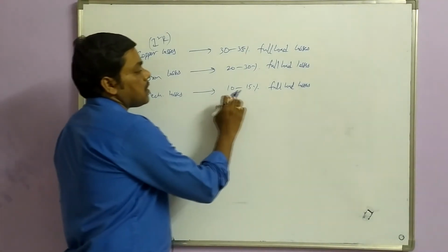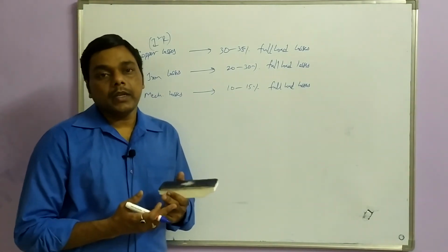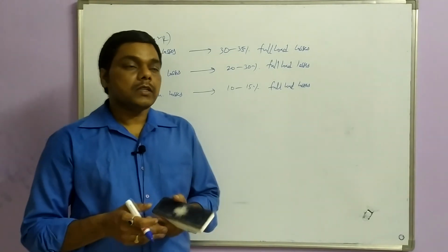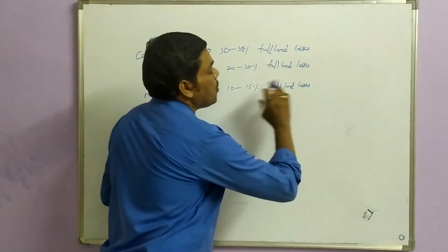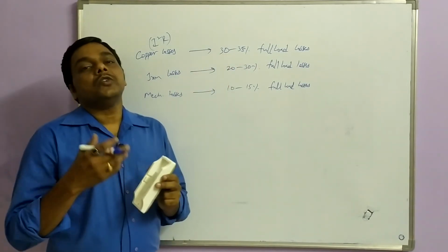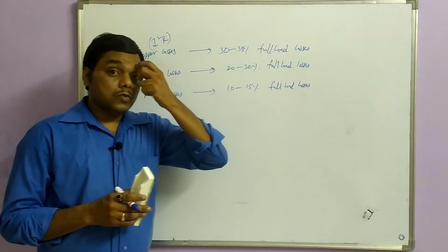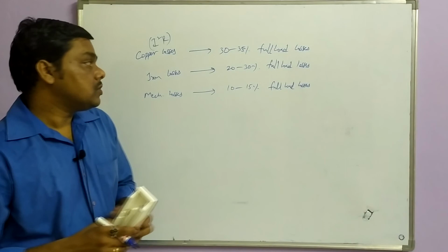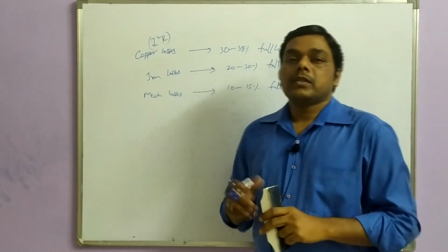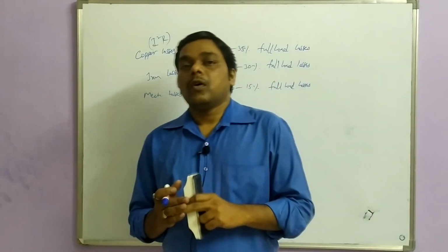They should be kept at a low value so that the efficiency of the motor or generator increases. The mechanical losses are less, 10 to 15%, and are reduced by regular maintenance, lubricating and greasing, and proper placement of the motors or generators. The major losses are due to copper losses, so by using high grade copper with low resistance, the copper losses are also reduced. Now these are the various losses in DC machines. Next, we will look at different conditions and the efficiency relation among all the parameters.